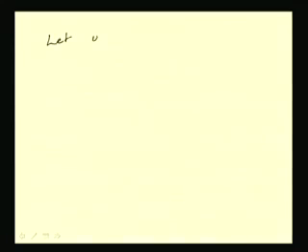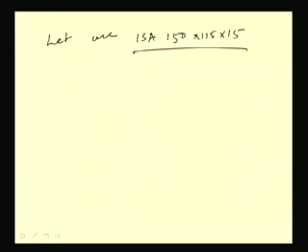So, now we will see with the increase of size of seat angle how we are going to make it safe. Earlier we have considered 100 by 65 by 10. Now, let us use say ISA 150 by 115 by 15. So in place of 100 by 65 by 10, let us use ISA 150 by 115 by 15.